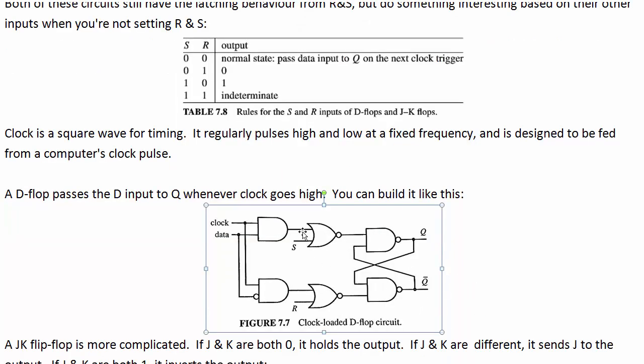Now, what happens when we put a 0 up here? Well, either by putting the set pin to a high, or this AND to a high, because clock and data are high. So if clock happens when data is up, or when we put set on, then we get a 0 here, and that pins this to a 1.